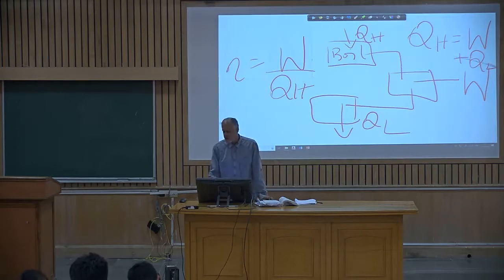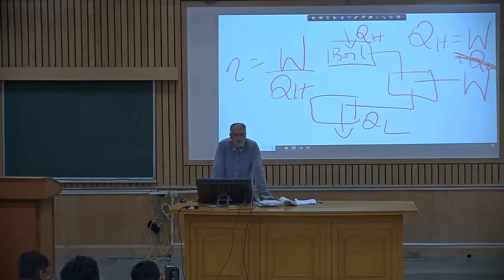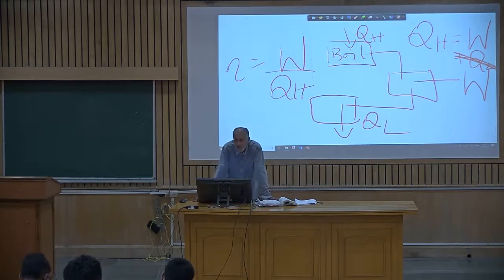So for this case, write the diagram. Convert this to a diagram where that entire heat is converted to work. Which Kelvin statement says it's an impossibility. It is an impossibility. You need to have heat being dispersed or discarded or dumped in the low temperature location, because the entropy of the surroundings has to increase. Otherwise, the process will not happen.